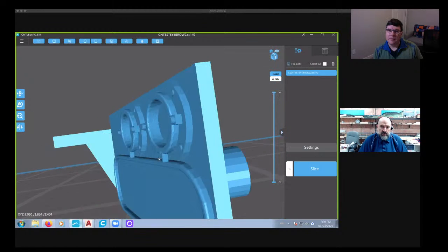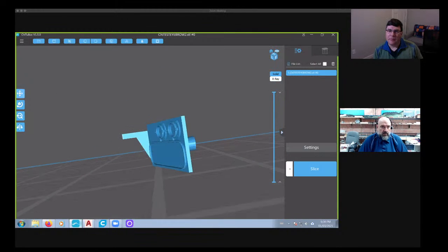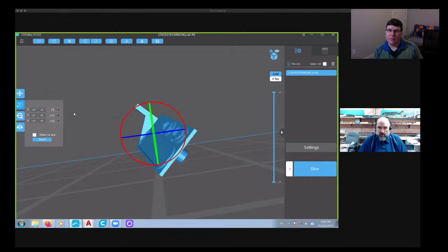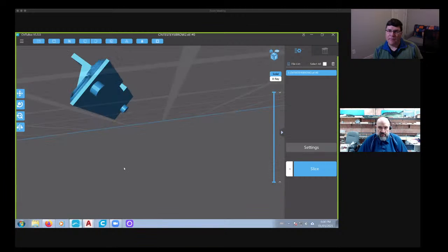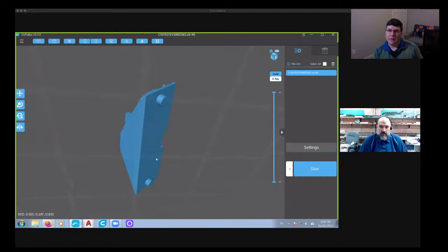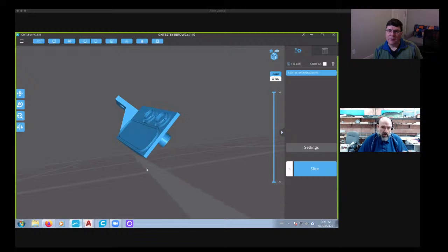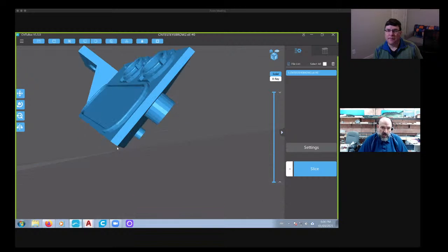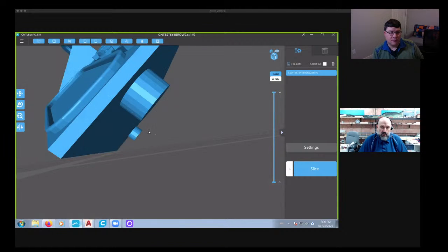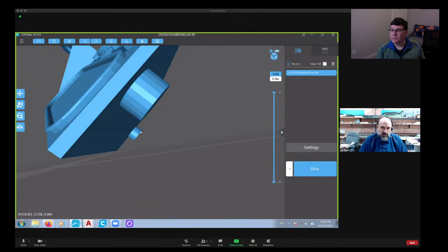Okay, so the next thing we're going to do is rotate it. Let's go 45 degrees. Okay, now we can see, because we want the model to build off of itself. Yeah. We got this edge here, right? Yep. So if we were to support the edge, and we have to support the 2 lower limits to these pegs, and then it should print okay.